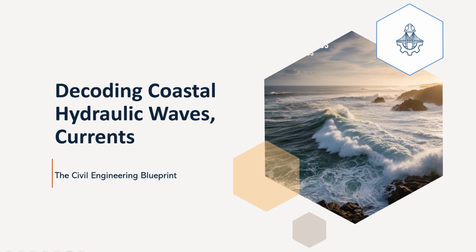Correct. The mechanism involves water particles moving back and forth, carrying their kinetic energy across this imaginary plane. They also have potential energy due to their position. Additionally, the pressure exerted by the wave does work on the water particles as they move across the plane. When we average this energy flux over a complete wave period, it simplifies to a very useful equation for the average wave power per unit width, often denoted P. P equals E·n·C, which is E·CG. Where E is the average energy density we just defined, C is the phase velocity, the speed of an individual crest, and CG is what we call the group velocity. The factor n relates the two: CG equals nC.